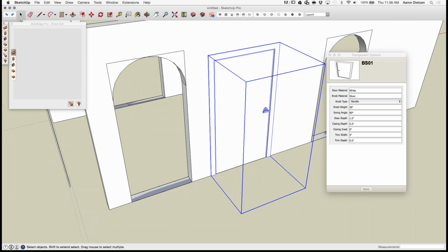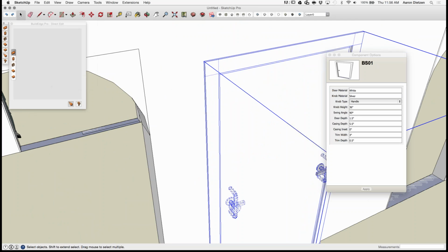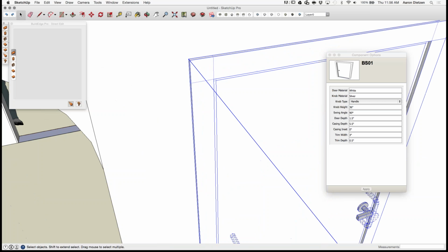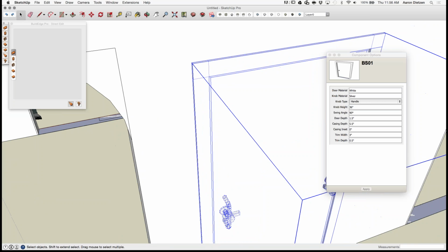The only issue that would come up, again, if I look at this, because of my hidden geometry, in order to make this work, this is actually multiple pieces, so you just have to know what you're going to do here. The reason this is a square is if I had this all solid one piece and this solid one piece, as it resizes, it wouldn't line up properly as the sizes change. The other thing that having it in these pieces like this lets me do is turn off the entire left trim or the entire top trim. So you could have a profile that you stretch along here, though. That is perfectly possible.